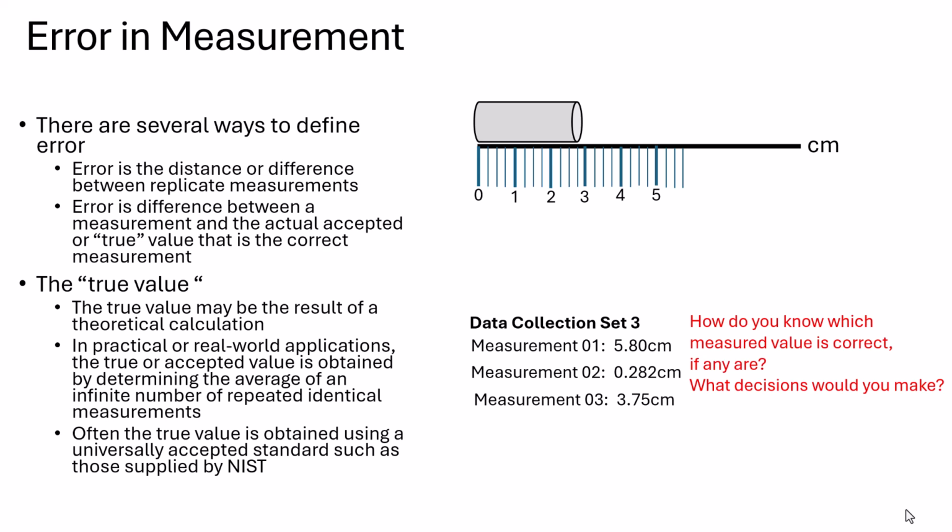And then once you figured that out, you would do a CAPA, a corrective and preventative action, right? So you would write up how to do this correctly. This could involve retraining. It could involve recalibrating the instrument, maybe even buying a new instrument and validating that instrument. But you would have to do something to correct the errors from this data set 3.